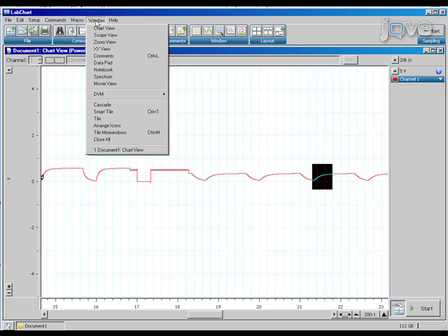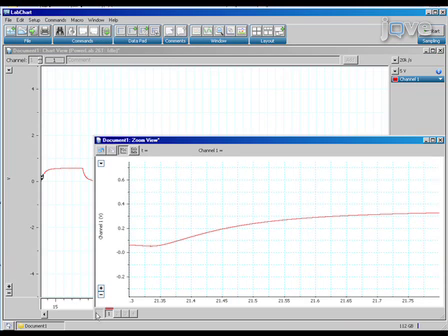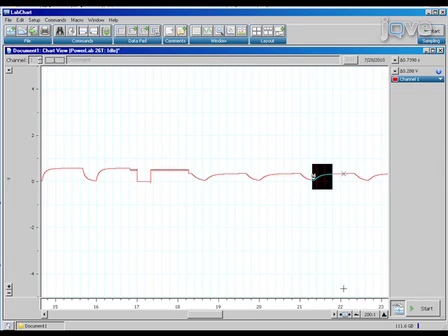After data collection, use the zoom window to expand the rise time on one of the square pulses. Repeat the zoom in as needed to spread out the trace. Measure the time it takes for the signal to rise from the baseline to the top of the voltage trace just as it levels off. Observe the time course of the potential change and the distortion of the square pulses. Also note if the voltage measured is above 0.2 volts.